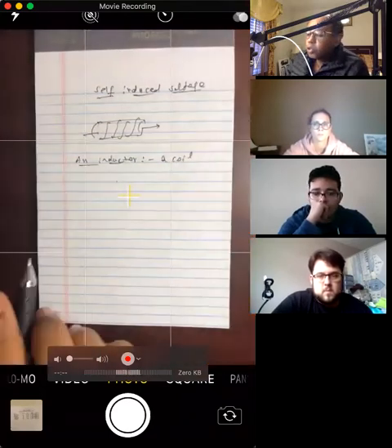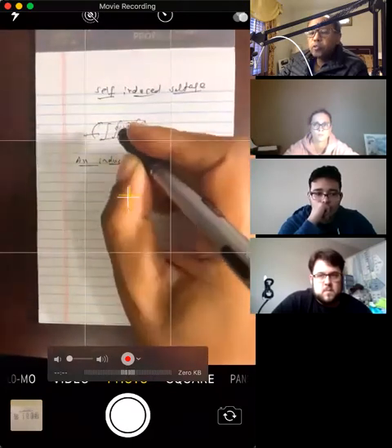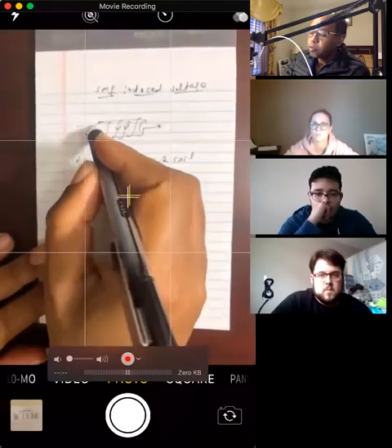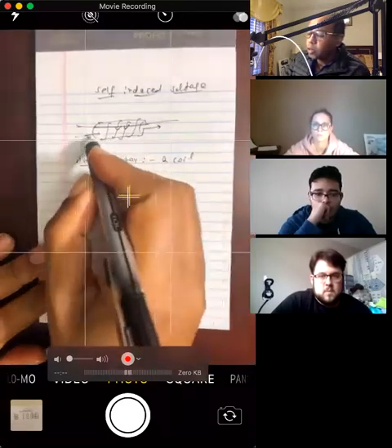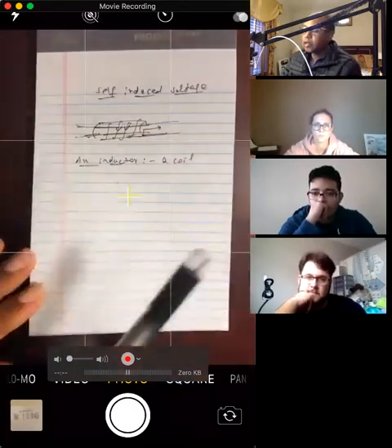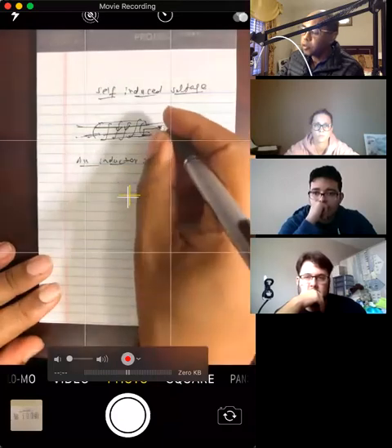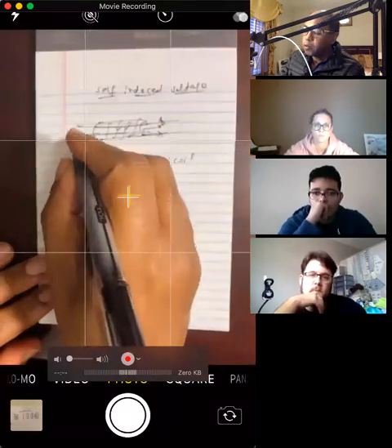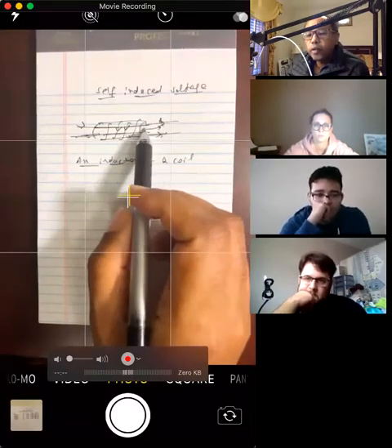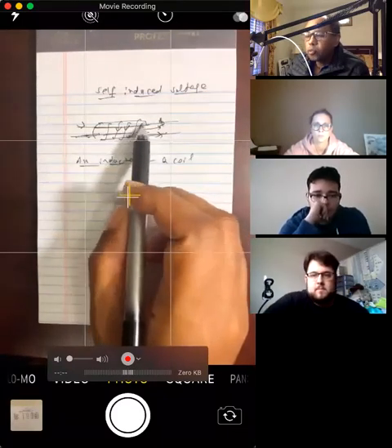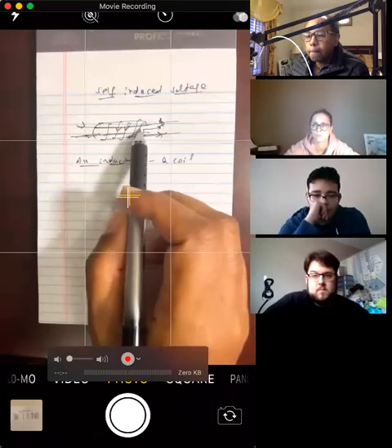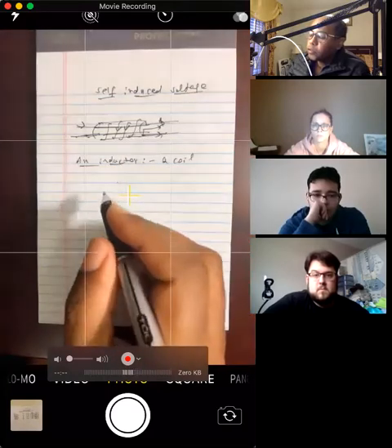Now, suppose this solenoid is carrying a current. It's going to produce a magnetic field of its own because of the current. If the current is going this way, then the field is going to go this way. So its own magnetic field is crossing the coils. So there's going to be flux due to its own magnetic field. This flux is called self-induced flux.